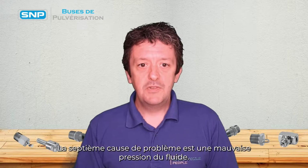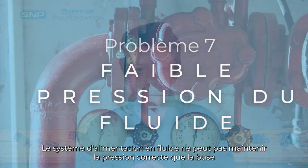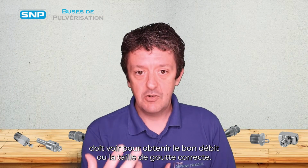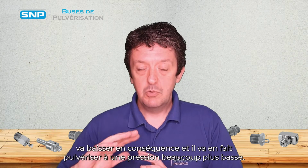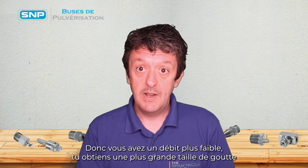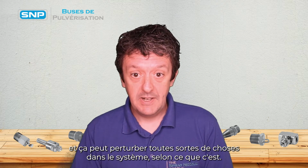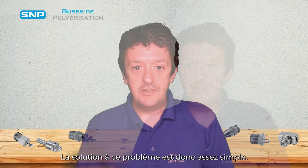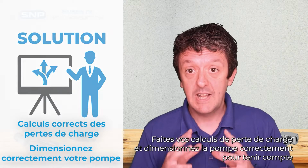The seventh cause of problems is poor fluid pressure. If the fluid supply system cannot maintain the correct pressure that the nozzle needs to see to get the correct flow rate or the correct drop size, then the back pressure from the nozzle will drop accordingly, and it'll actually be spraying at a much lower pressure. So you'll get a lower flow rate, you'll get a bigger drop size, and that may mess up all sorts of things within your system depending on what it is. So the solution to this is quite simple. Do your pressure drop calculations and size the pump correctly to account for them.